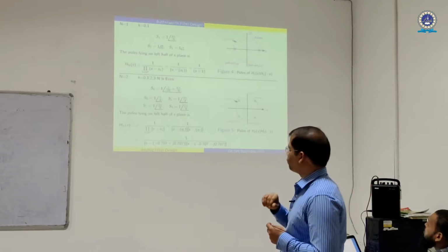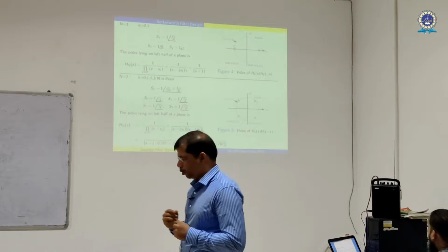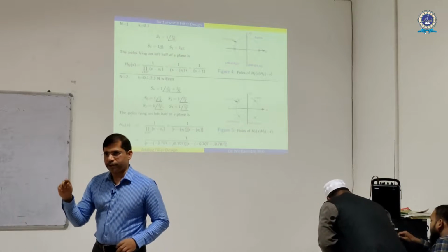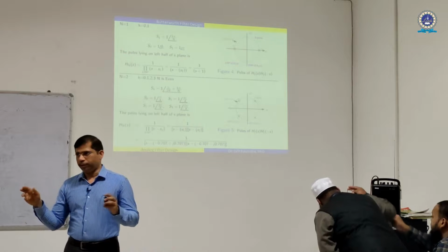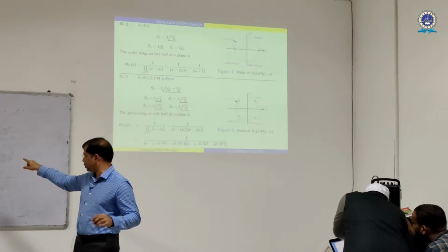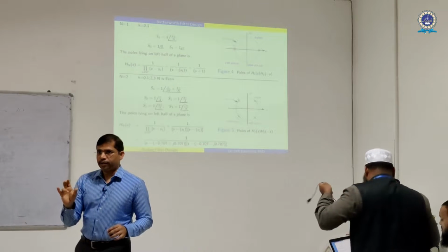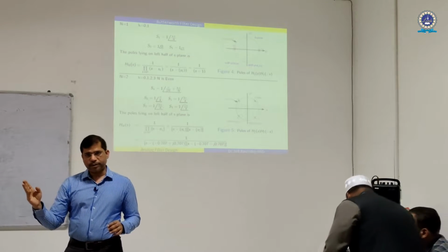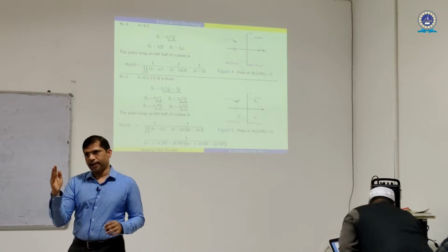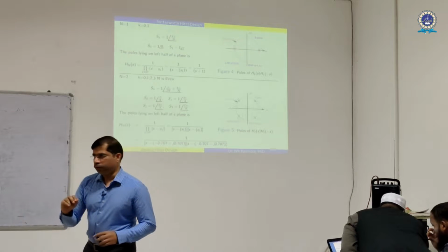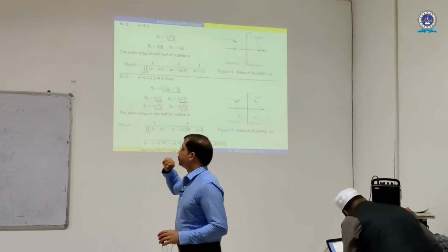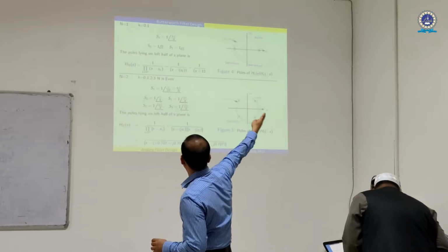Yes. Now the point is, what is that equation given for? That is 1 by 1 plus omega by omega c whole power 2n. So omega c will be given to you. That means the cutoff frequency will be there with us, right? And omega is also there. So for various frequencies, by putting the omega c value, you can always calculate the order of the filter. So this is what he has actually done. For n equal to 1, if you substitute that, you have one pole here.